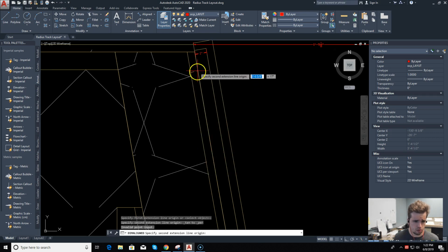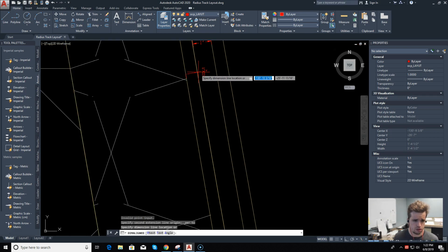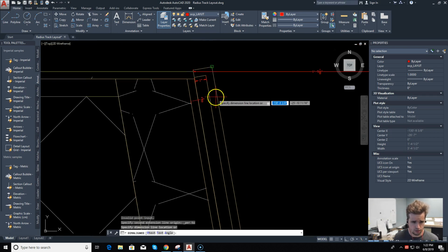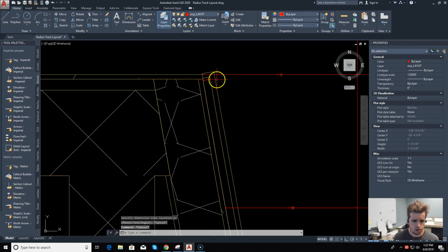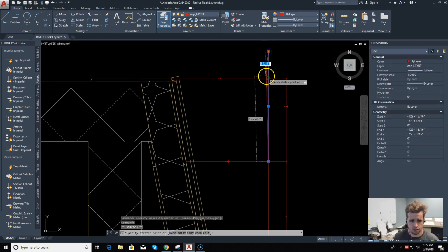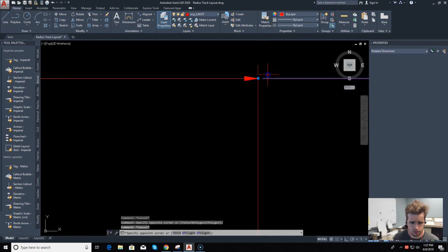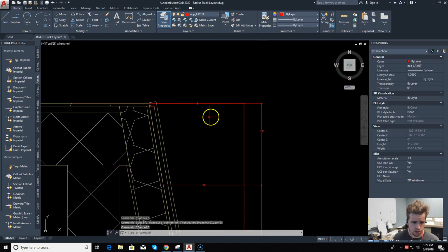You have 5/8 of gyp board. That's not what I wanted. There we go. 5/8 of gyp. And then you have this 1-inch cavity, and then another 5/8 of gyp with this weird return. So I want to make sure that the guys in the field understand that that is there, just so everybody's on the same page with what we got to do.